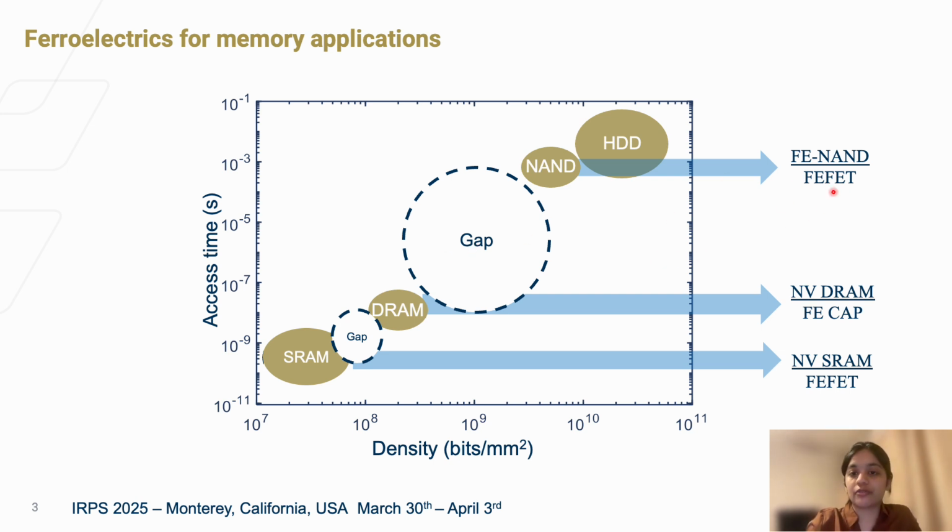So we have the ferroelectric FET that can act as ferroelectric NAND, and we also have the ferroelectric FET acting as non-volatile SRAM applications, and we also have the ferroelectric capacitor for non-volatile DRAM applications. In this talk, I'm going to be specifically talking about ferroelectric field effect transistors.